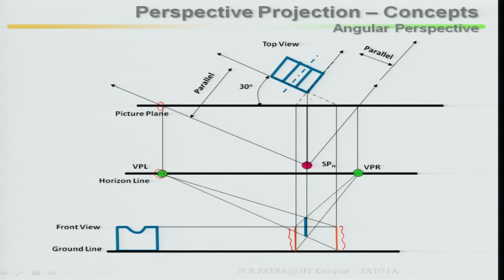The case is this entire object is far away from this. Then from this edge you project it back. Once you project it back, because this is a right face, you join your vanishing point of your right. Because this belongs to your left face, the left edge, join back to your vanishing point of your left. Then once you join, you will get intersection points. Here you are getting this one intersection, here you are getting another intersection.